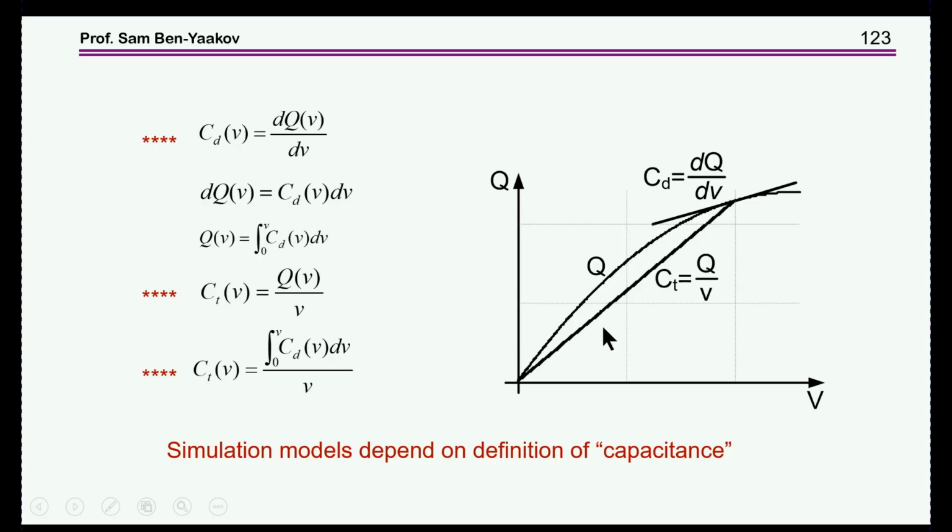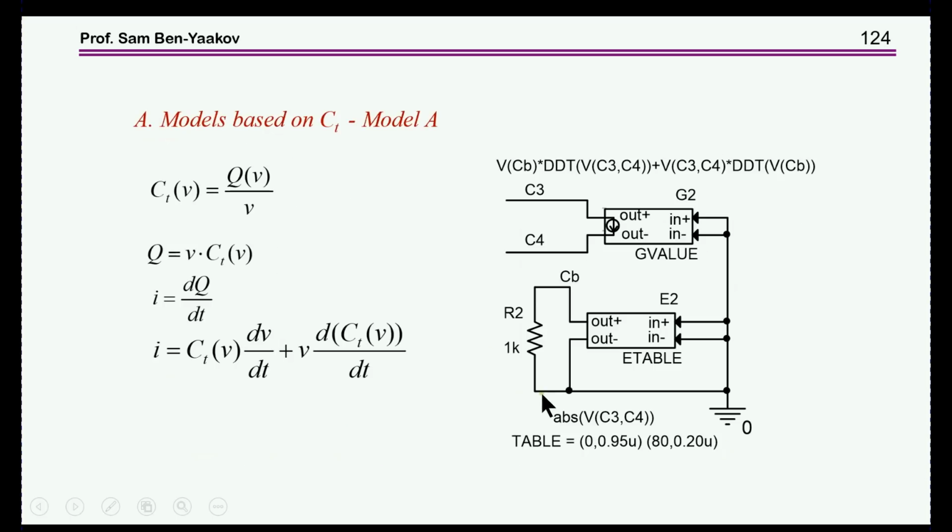AC is a little bit complex, so the two neat ones are either the derivative, that is the local one, and we have the curve very nicely of how this local capacitance is changing with voltage, or the total, which can also be obtained from the Q curve, or it's CAC with zero bias. So there are many ways to do it, and let's go over them fairly quickly.